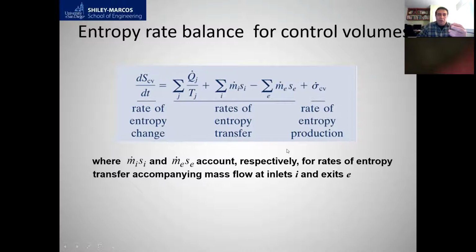And we can always simplify the governing equations, the original equations, with the simplified equation, and you will see that it's based on assumptions that we make, because the value of each term, like potential energy or sometimes kinetic energy or inlet velocity, is very insignificant compared to exit velocity in the case of a nozzle. So, this is the entropy rate balance for a control volume, okay?